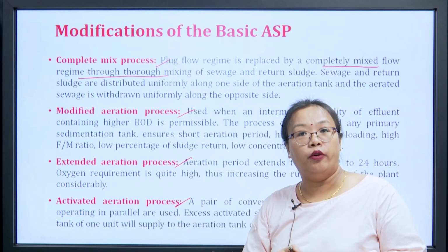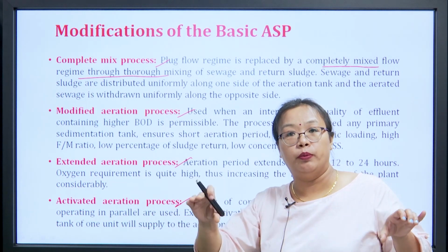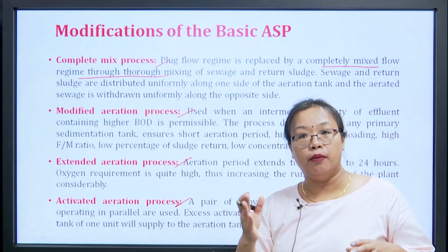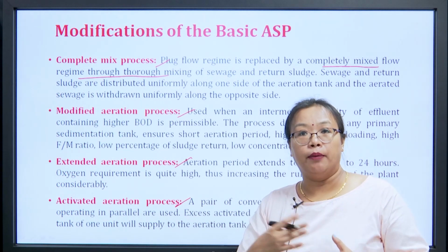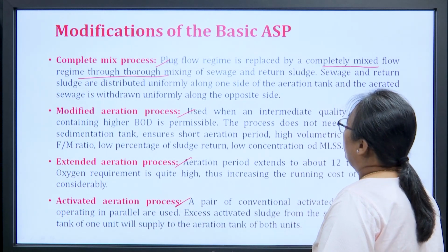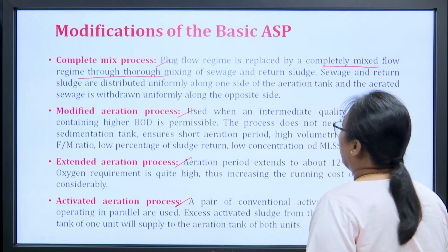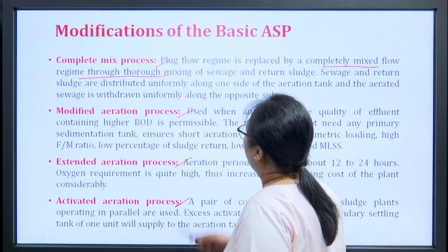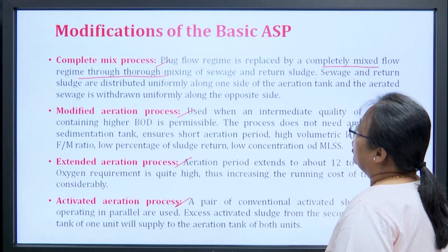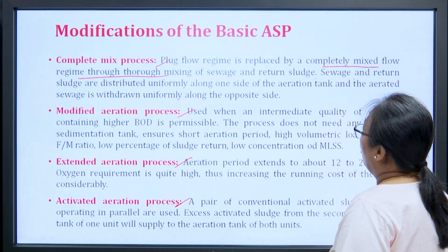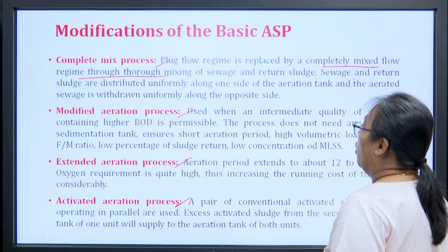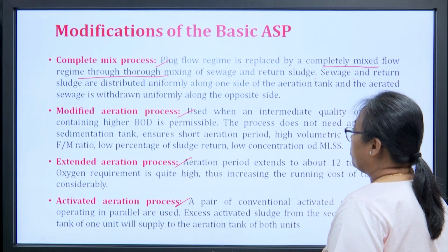So generally plug flow reactors will be like a pipe, longer, like a long rectangle, whereas in a completely mixed flow you are mixing everything completely in a very uniform way, right. So plug flow regime is replaced by completely mixed flow regime through thorough mixing of the sewage and the return sludge. Sewage and the return sludge are distributed uniformly along one side of the aeration tank and aerated sewage is drawn uniformly along the opposite side, right.